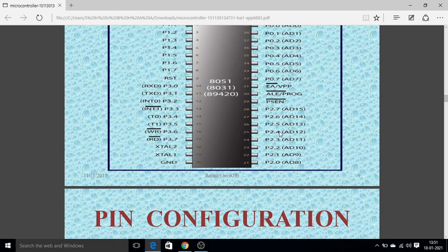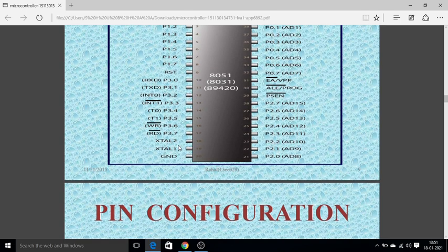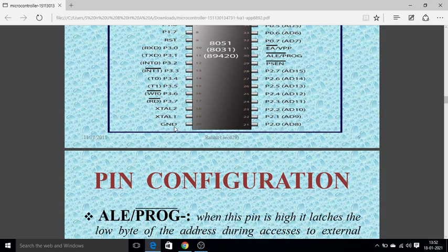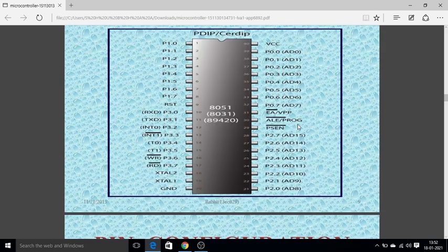And this external clock is an externally applied clock signal, defined by the two capacitors, and here we have the two capacitors. This will be external 1 and this is external 2, so that it is an external clock frequency to generate the 12 megahertz of frequency. This is ground, and VCC is going to be given 5 volts.